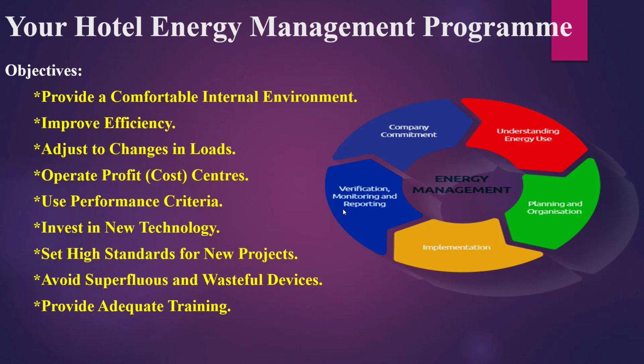Improve efficiency. This requires operators to understand, operate, and maintain the hotel's energy-consuming equipment and systems in an energy-efficient manner. Efficient buildings, equipment and systems consume less energy and cheaper energy to accomplish their task. Energy management is a continuous learning process. There are often enhancements you can make to improve the efficiency of your equipment, and the way that you operate it. Regular efficiency measurements should become a standard procedure for major energy consumers such as boilers, chillers, cooling towers, and air handling units.